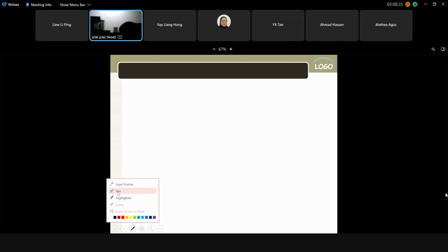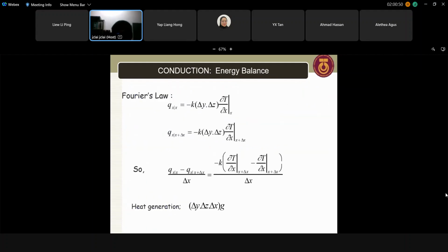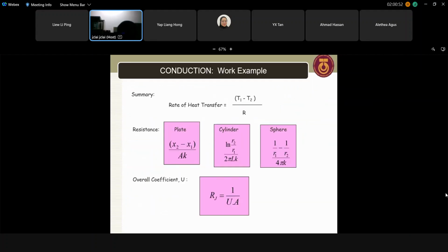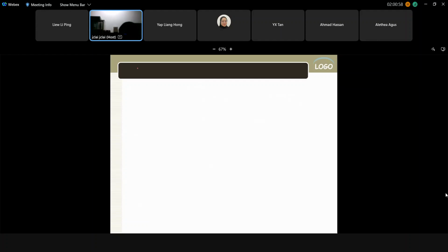So in such a case, now you have 4 surfaces which are the same with same thickness, right? Let's see. You see the basic formula for R is x1 minus x2 per A. Let's take this: R equals delta x per A K, right? A being different is okay, right? Because A you can just calculate, but X,